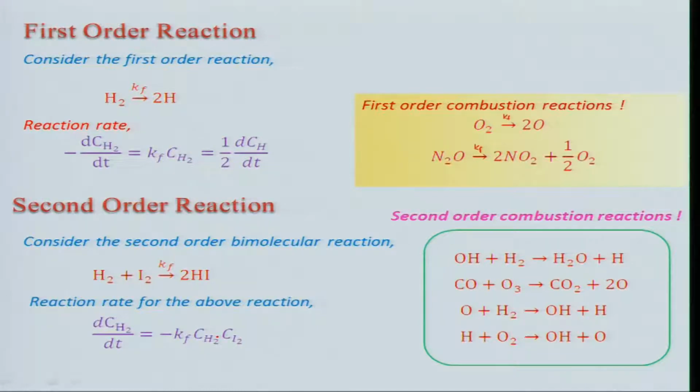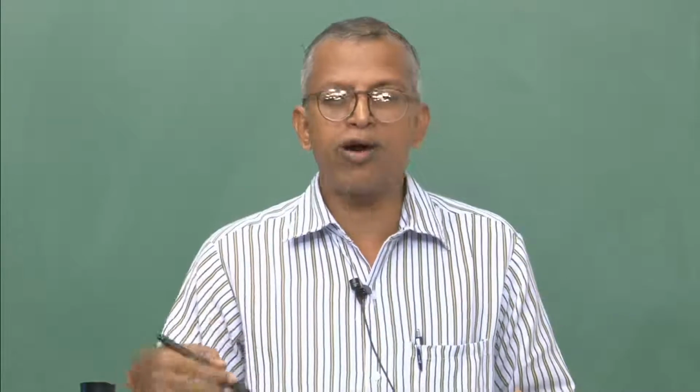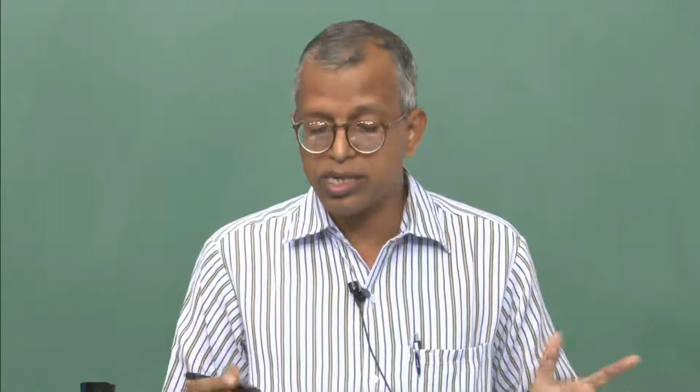If you look at the reactions involved in combustion, many are second order reactions. Some examples I have given: OH plus hydrogen going to water plus H, O plus H2 going to OH plus H, and H plus O2 going to OH plus O. There are several reactions which occur even in hydrocarbon and hydrogen-oxygen systems, and all of those are important. These are second order reactions, right.